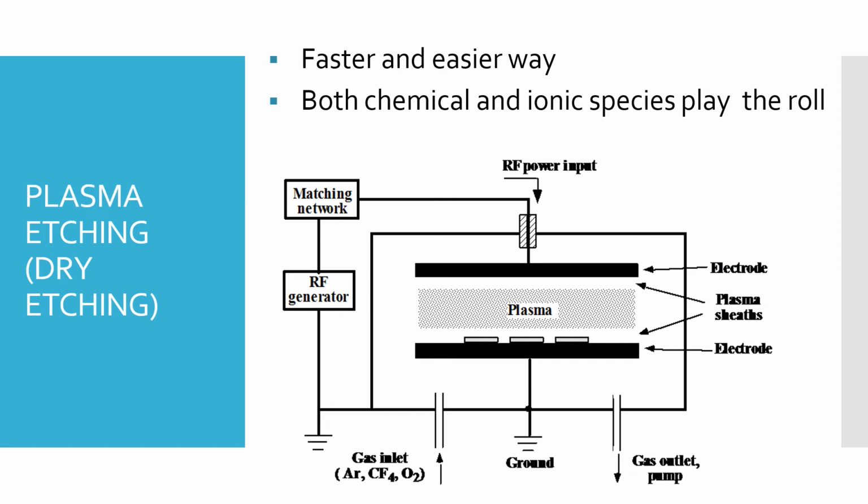Okay, so reactive species diffuse to the surface to be etched and then absorb on the surface. Once the reactive species reach the surface, they move around on the surface. This process we call surface diffusion, until they react with the exposed film. Afterward, the product of the reaction will dissolve from the surface and then diffuse away through the gas stream. In some cases, the sample's temperature is intentionally elevated to increase the volatility of the products.